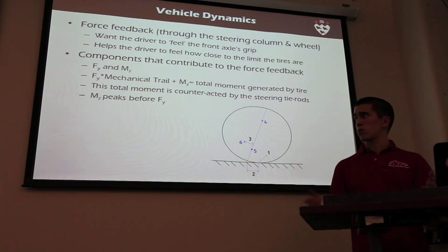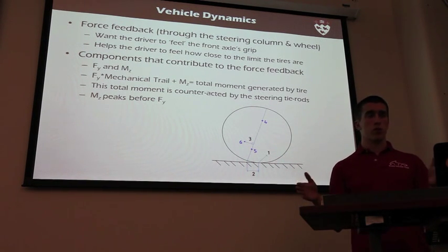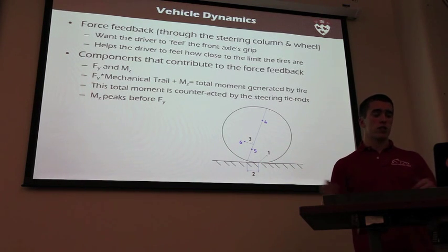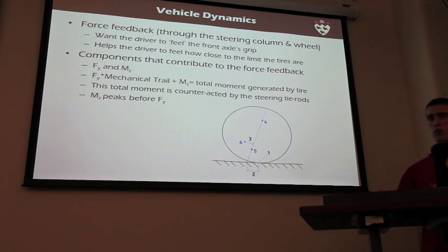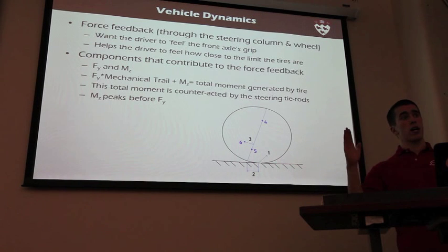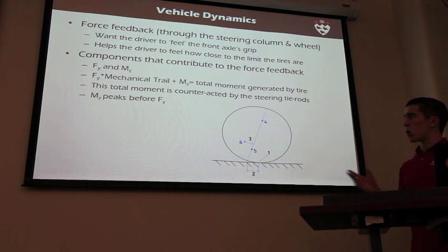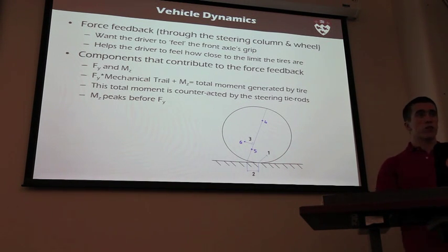So basically we use OptimumK, a simulation software that simulates the geometry of the suspension, so you can simulate when the wheels have a 30-degree angle, how many degrees of camber I will have. Then couple that with the tire model that we have, we can see how the tire reacts to such a positioning, and then we can see if it's better or not.